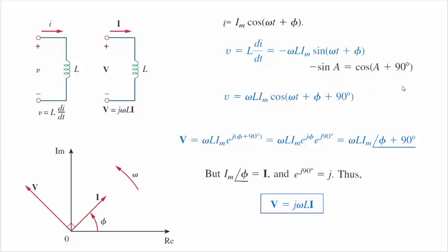We apply a trigonometric identity, and then we continue doing the math. So here it is as a function of time. I switch back down here in the next step, because we want the phasor notation in the end. We switch it now into our phasor notation, which is our exponential notation, keeping in mind that e to the j omega t is always implied in here. And so continuing on, bringing out the 90 degree phase shift. Now remember that e to the j 90 is like putting j in front.